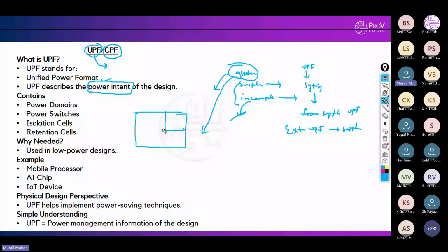One is the power domain. So this is P1, which will work with 0.1 volts. This is domain 2, P2, which will work with 0.2. Whatever standard cells have a threshold voltage of 0.2 will come and be placed there. Like this, the power domains will be defined. Then power switches: with the help of power switches, we can control the power consumption, like power dissipation.